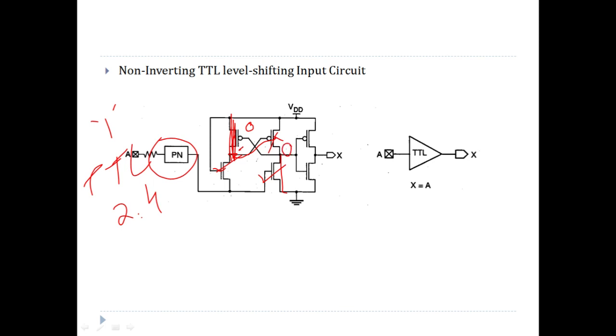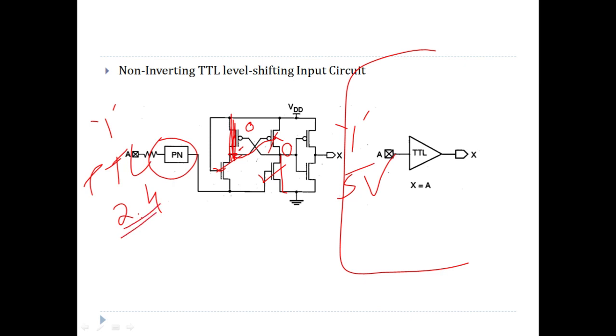Okay, so at the input of this inverter there is a 0 volt, so it will invert this 0 volt to give you logic 1, which will be compatible with the CMOS logic that you have implemented, that is 5 volt. So the 2.4 volt that you had at the input of this has been converted to 5 volt. Typically the threshold of this will be very small, like 1 volt or something. So even if it is 2.4 volt, it will be treated properly as a logic 1.